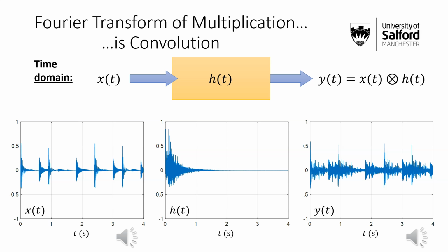Our impulse response was causal. It only goes into positive time, which means it only smudges to the right. But if you had something with values for negative time as well, or it might not be time that we're smudging with respect to, then you get smudging in both directions. And they use this in image processing for blurring.